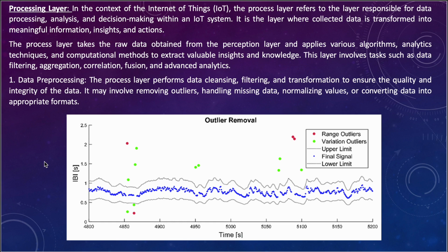So if you dive into the documentation of each sensor, you will see that there is such information given in that. Here you can see that there are these dots which represent data points which are being collected, right? And when collecting data points, we know that there will be background noise or white noise also, if you talk about frequencies and those things, right? So there should be a process to get the raw data and filter it out, do the needed calculations, apply the needed filters to get a proper value.